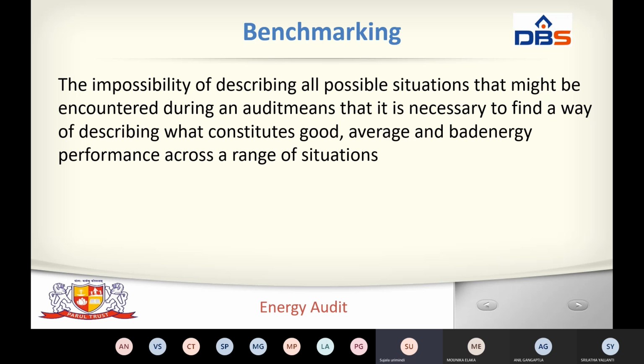First, the building will be compared to similar buildings. That means the preliminary whole building energy use will be analyzed based on the history, utility use and cost, and the comparison of the performance of the building to those of similar buildings.